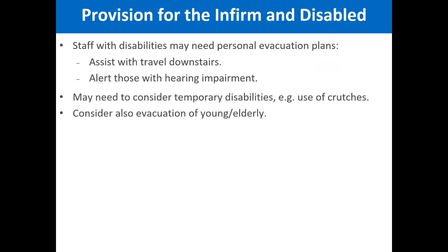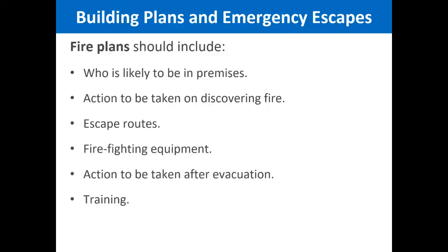You need to have provisions for the disabled people as well. For example, a person who cannot hear, okay, so you need to have a flashing alarm for him. If he cannot hear the fire alarm, he will be stuck and he will die. So you need to give some consideration to that as well. You may need to consider temporary disabilities, consider also the evacuation of the young and the elderly.